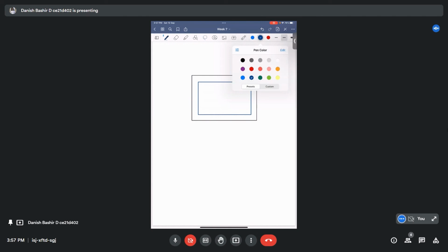We will have longitudinal bars at 4 corners, 25 mm bars. This is main bar 1 here, another main bar here, another here, and one here, showing with one color. So the color coding here is 25 phi longitudinal bar.